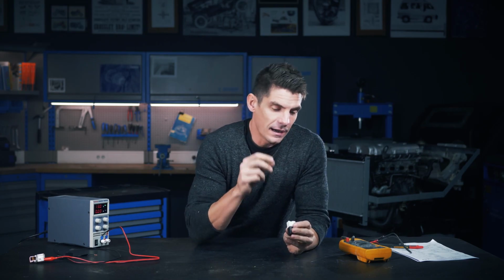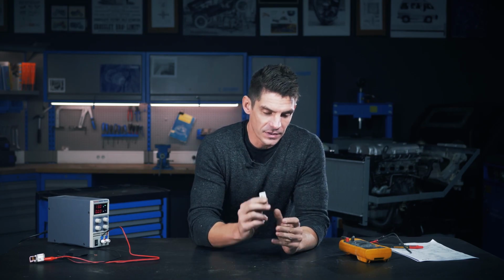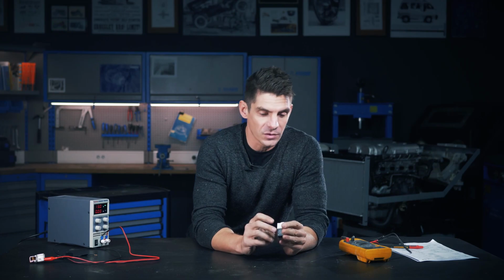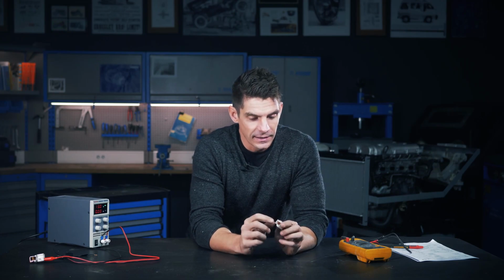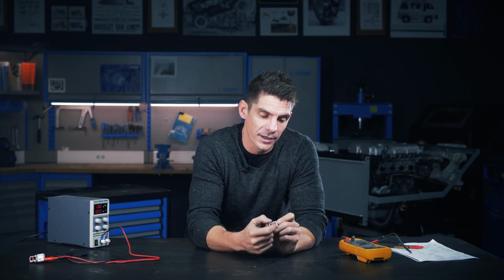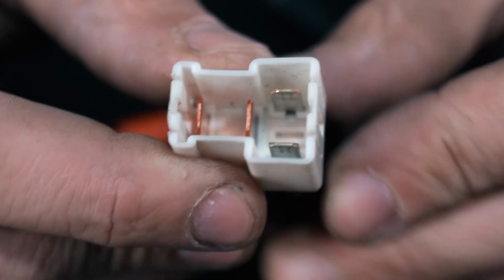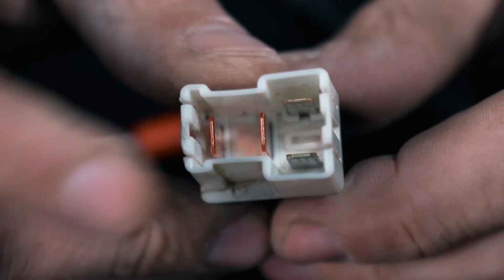Now, you can look up a wiring diagram for these ISO relays. They're all of the same type. A mini relay, no, this is a micro relay. A micro relay like this one, in either case actually I think, they have different sized terminals. So the smaller terminals, or the thinner wires coming off this, are always going to be the supply to the coil, whereas the bigger terminals, 6.3 millimeters I think on this one, are the main current, the switched current, the high current side of the coil.